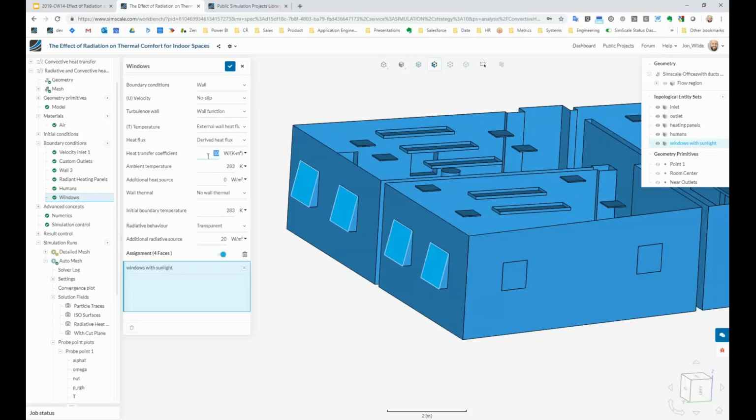we would basically set up a heat transfer coefficient. So this is heat being lost to the external environment. A value of, say, 5 watts per meter square Kelvin, up to maybe 10, would assume something like natural convection outside, and this is our ambient external temperature. If we make this something like 20 or 25, now the flow outside is going to be moving a little bit faster with the same temperature, but it means heat will be lost a little bit faster. So this is only heat being lost.